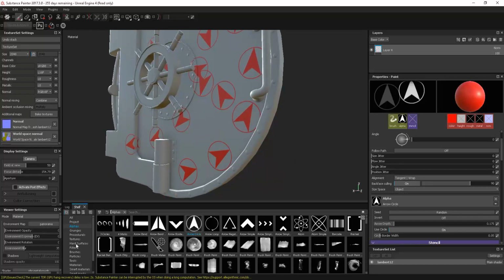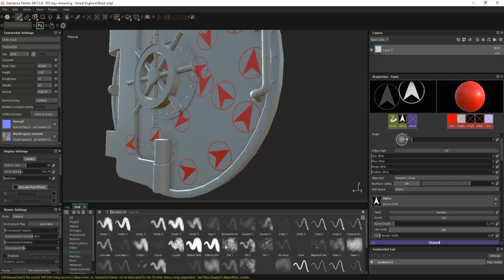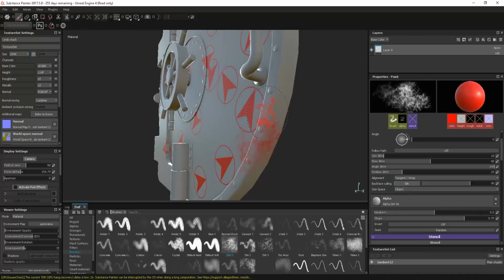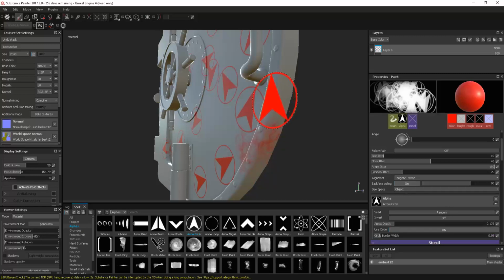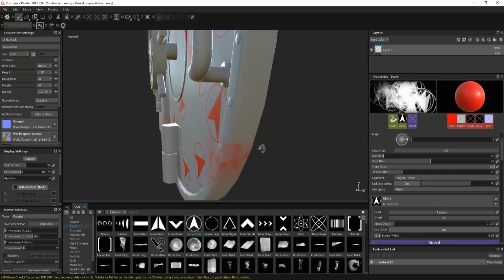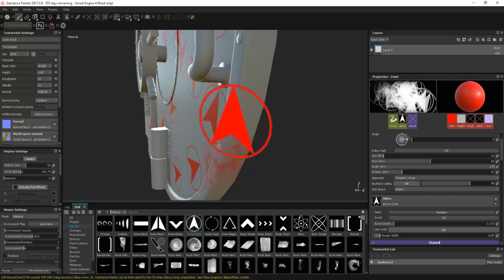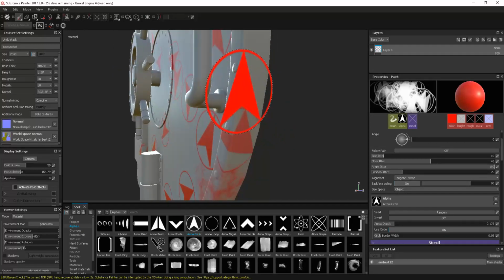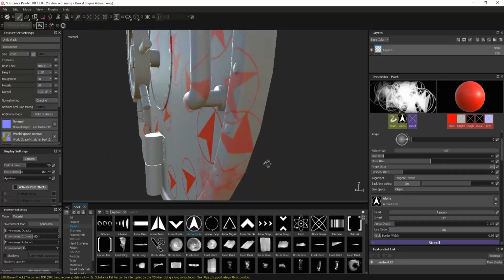Let's go back to my brushes. Let's maybe take a dirt brush. So by default, this is clicked to tangent wrap, and this just means that it's going to allow the brush to follow around. And again, I might just show this in an alpha, make a little more sense. So when we start going round, changing over the surface normals, you can see that brush will align itself to the object normals there. So if I go kind of over that, it's going to paint over both of the sections of this, like that.